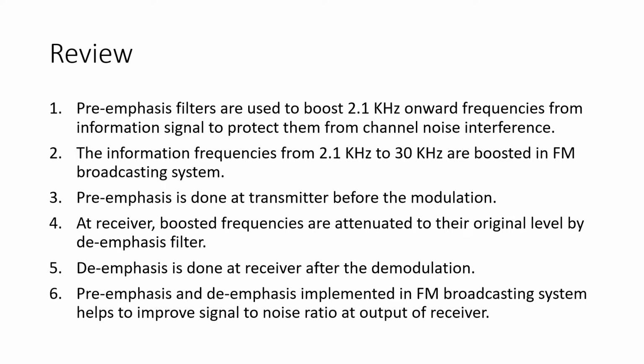Pre-emphasis is done at transmitter before the modulation. At receiver, boosted frequencies are attenuated to their original level by de-emphasis filter. De-emphasis is done at receiver after the demodulation. The pre-emphasis and de-emphasis are implemented in FM broadcasting system to help to improve the signal to noise ratio at output of the receiver.